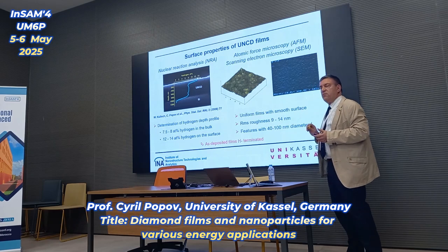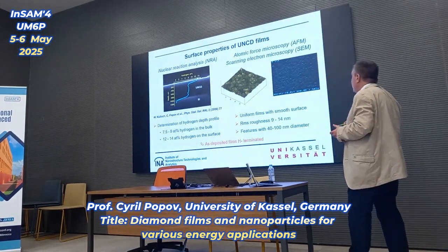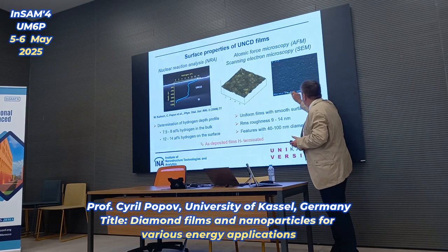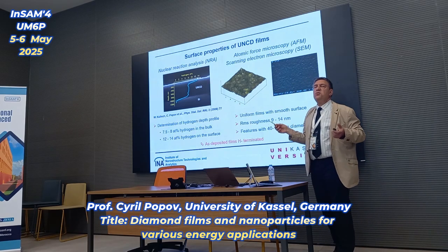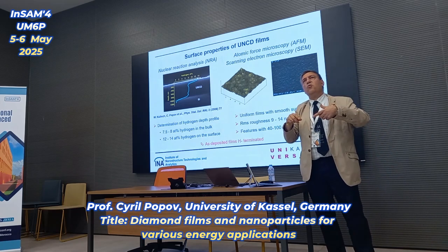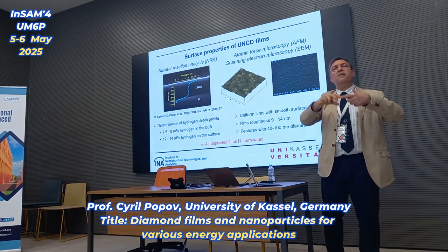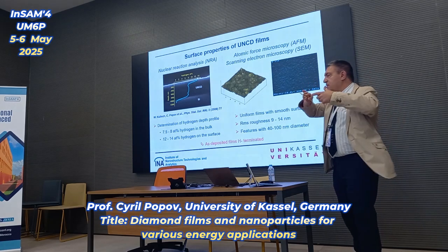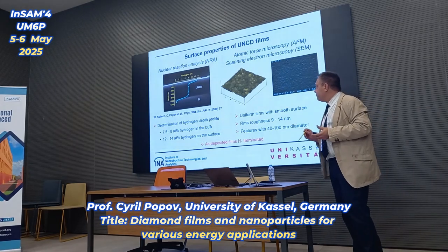So this is measured by atomic force microscopy, showing lower surface roughness, and you see some rounded features. So this is due to the growth mechanism. Nuclei, we start the growth, then we interrupt the growth, few more nuclei are created, and that's why it forms something like cauliflower structure.